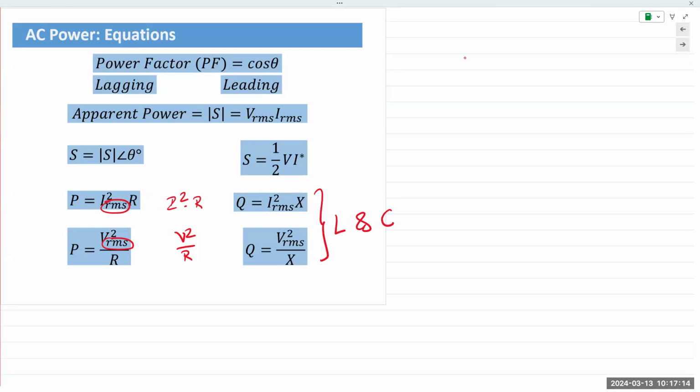Power is the product of the voltage and current, V times I. So if you think back to chapter 1, if we wish to find the power for a resistor, we would find the voltage for that resistor, find the current for that resistor, and take the product. VR times IR, P equal to V times I, would give us the power for that resistor.